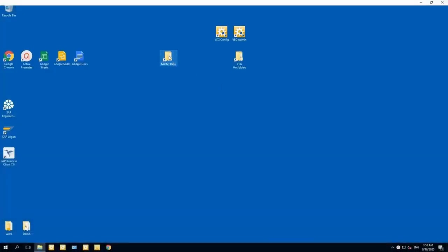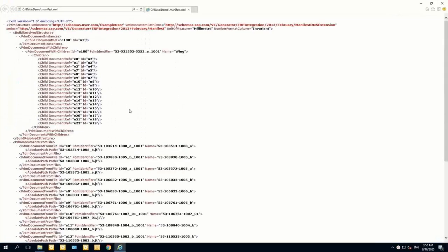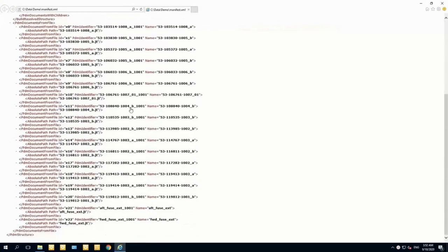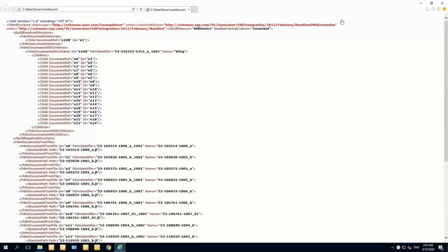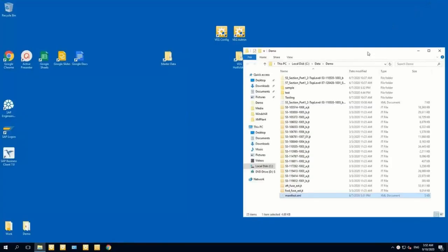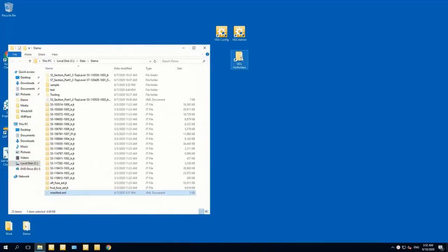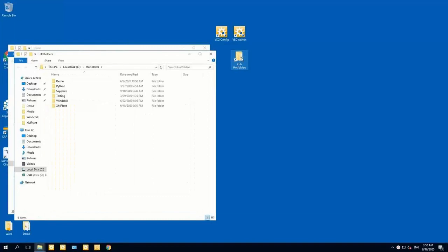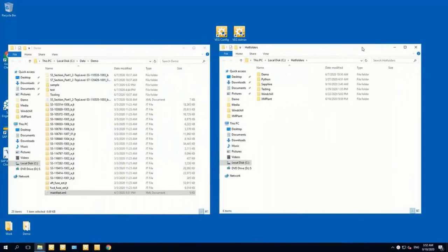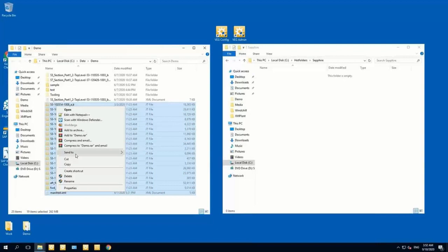And what's happening here is I've got a folder which has externalized CAD data from my PLM system. It contains my master CAD data and a manifest XML file. Think of a manifest XML file as a roadmap for the BOM for Visual Enterprise Generator. Think of Visual Enterprise Generator as a scriptable conversion engine. So what the logic does is it externalizes the release. We trigger upon a workflow event, like a release event, and it externalizes that CAD data into a folder. It creates the manifest XML file. It zips them all together into a single file, and then it copies them to the VEG hot folder.